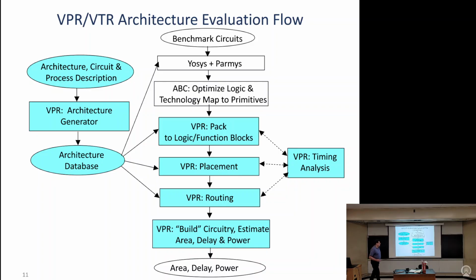Timing driven means that you can estimate delays for all the different parts of your circuit. You can send them over to a timing engine, and you can say, tell me what the slack is, and give me an estimate. Well, you can get essentially a slack on every single connection in your design. So not only do you get how fast is this design overall, if my guesses for delay are correct, but you can also see how much slack do I have in every connection. And that allows you to see, well, you have almost no slack, right? So I need to really prioritize. Try to change the placement and get this connection shorter. This other one has a lot of slack, I don't really care about it, right? I care about it for wiring, but not for timing.